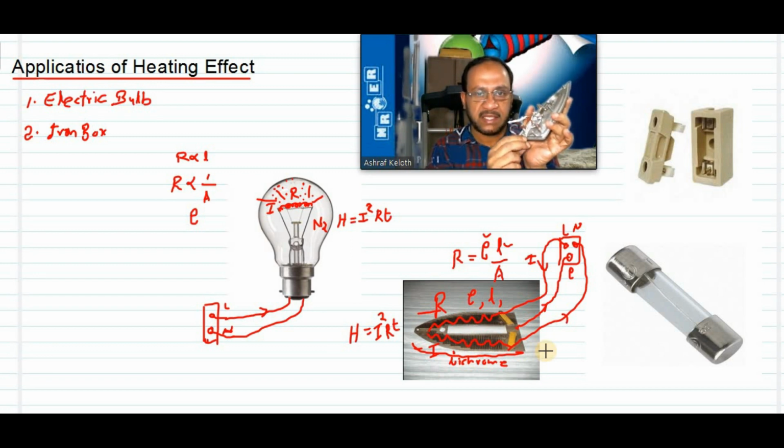If it happens like that, got the point? If the wire is coming in contact with the metal surface, normally it won't happen. By mistake, if it happened, then the wire insulation will be melted, and the inner copper will come in contact with the outer metal surface. That time if you touch here, you will get an electric shock.